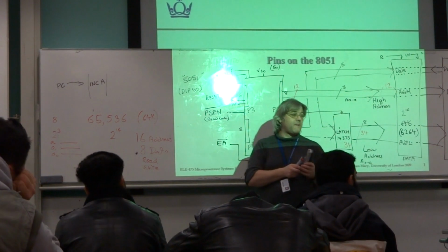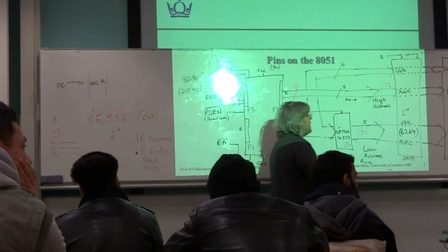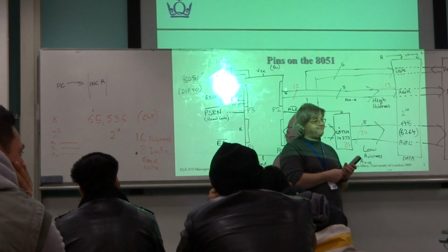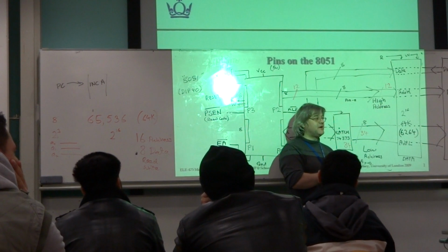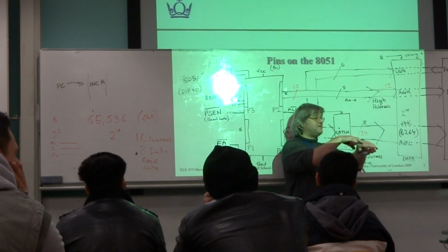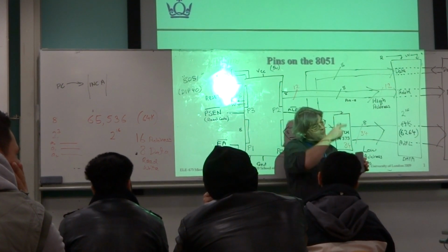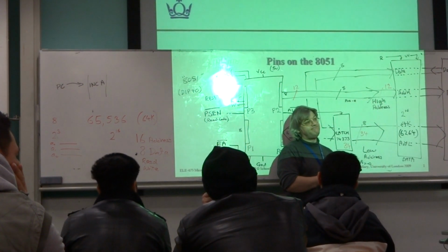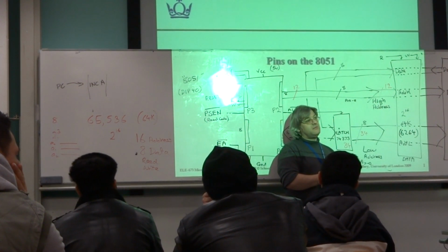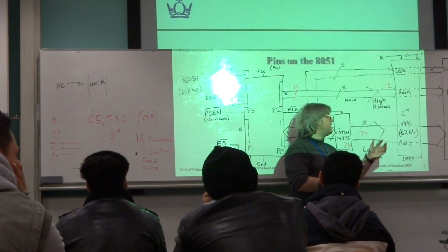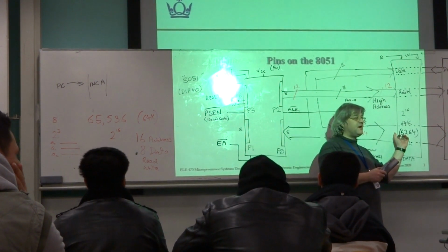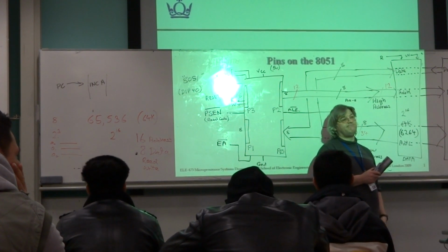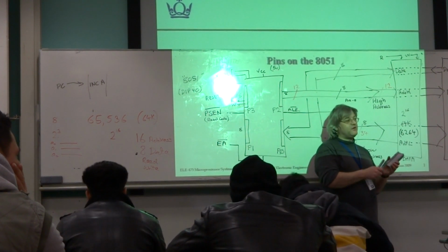I mean through, like, the initial programming, not at runtime. While you're programming it, can you program through it too? Well, I don't believe there's some kind of circuitry inside the 8051 that would allow you to go through it in a kind of data chain to some external device. There are versions of the 8051 where you can use I2C or SPI and things like that to write to some electrically erasable memory. But in terms of what you're asking, I don't think it's possible.